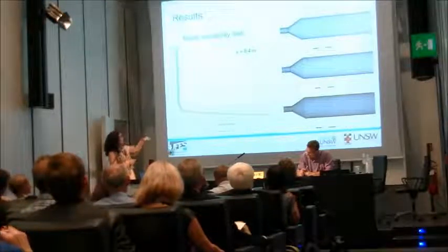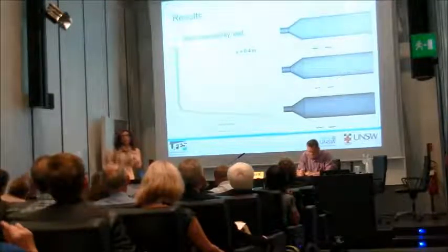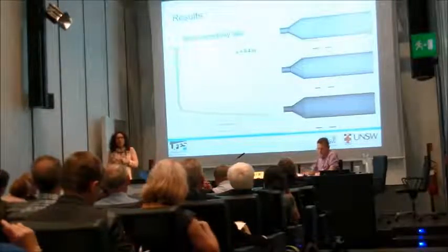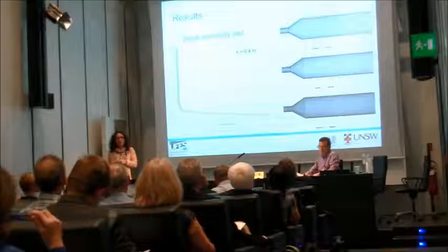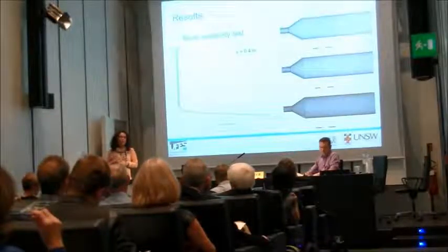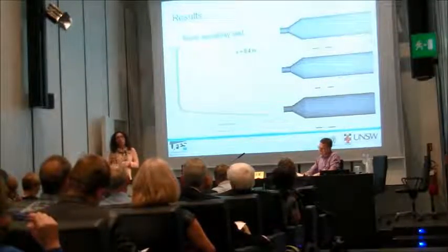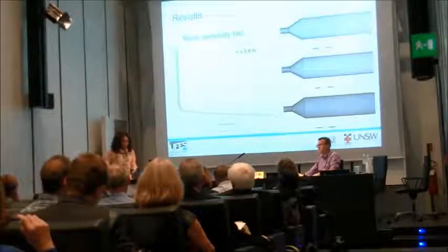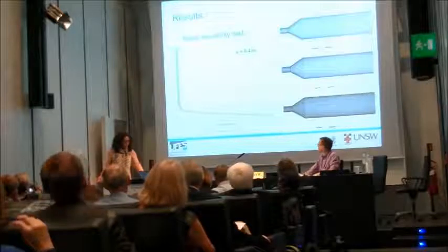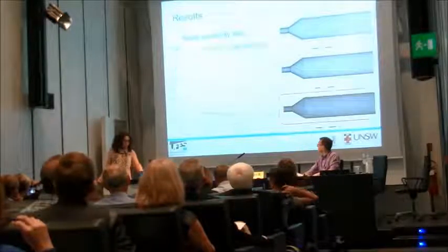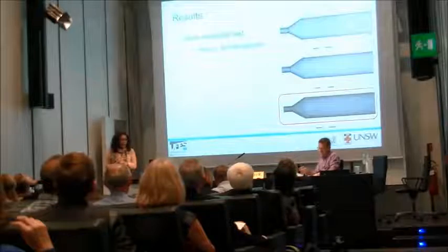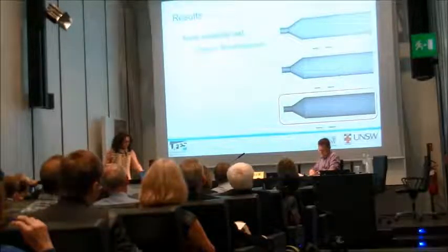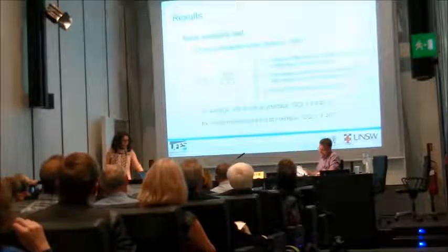Here we did the same for concentration, because in numerical solutions you usually get mesh independence easily for velocity, for the momentum equation, but for the concentration equation sometimes you don't. So you have to check both variables. We could choose any of the three, but we decided to use the most demanding one, the largest mesh.